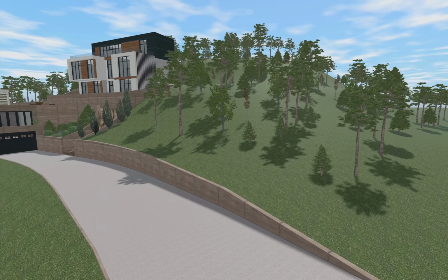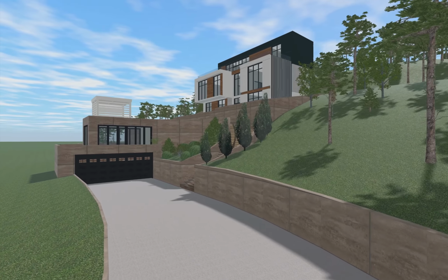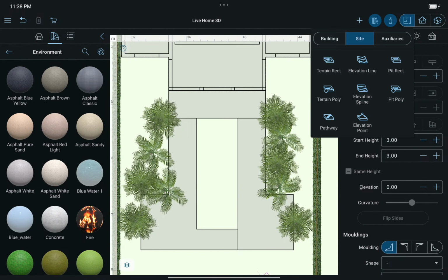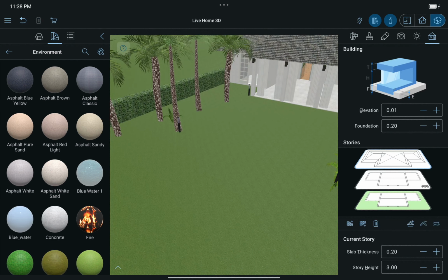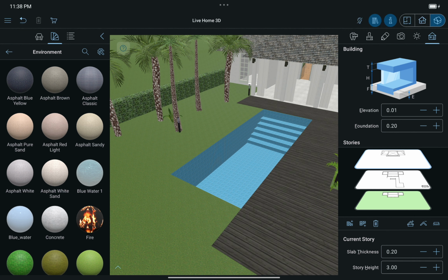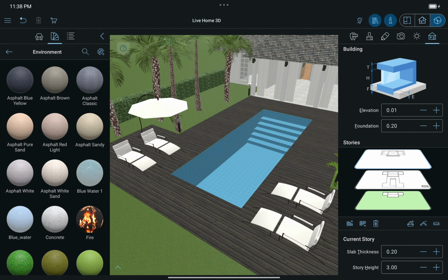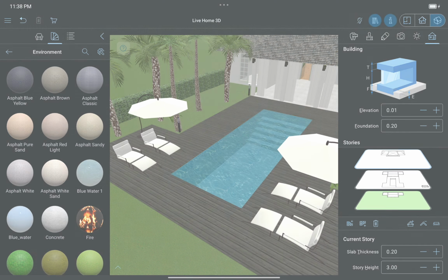The Pit tool is mostly used to add cutouts in the ground, such as garage access for houses on the hill. But perhaps the most frequent use for the Pit tool is to create swimming pools. To make a pool, I need to make a cutout in the ground, apply a material to each side accordingly, add side elements and steps with the help of shapes or the building blocks, add a plain surface imitating water, and finally, apply water material to it.